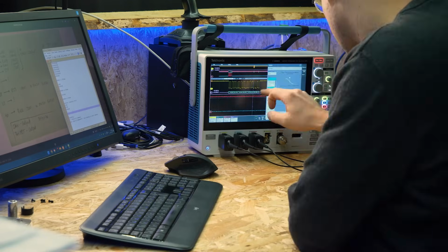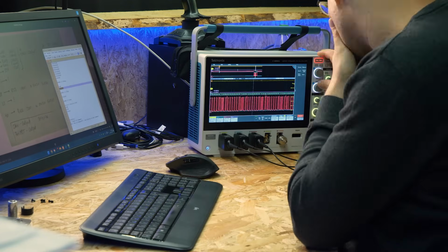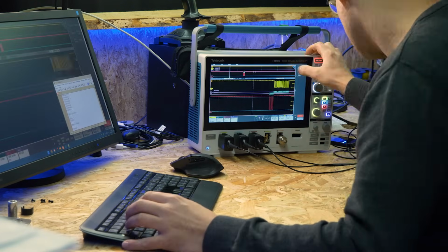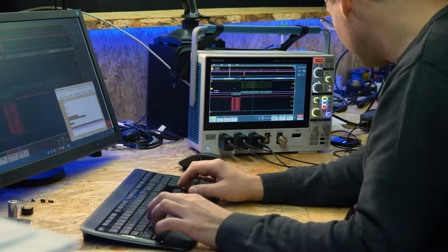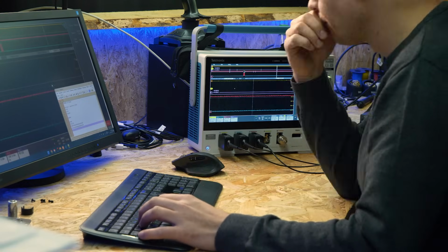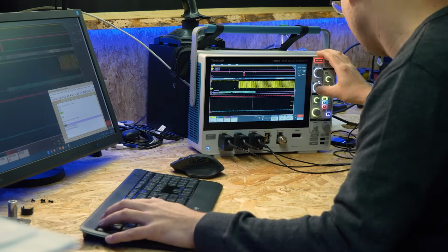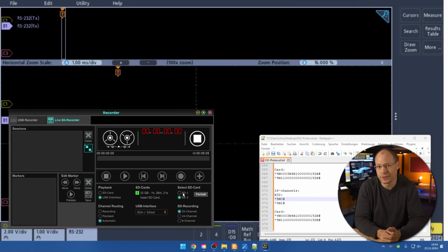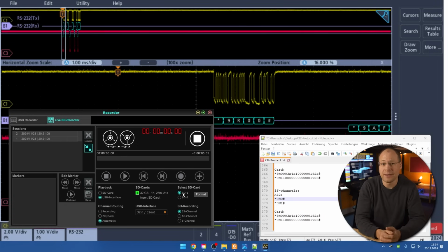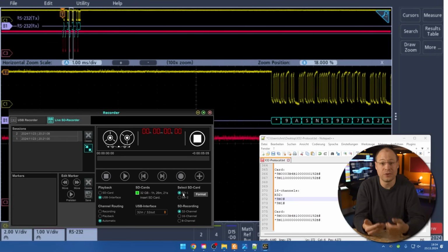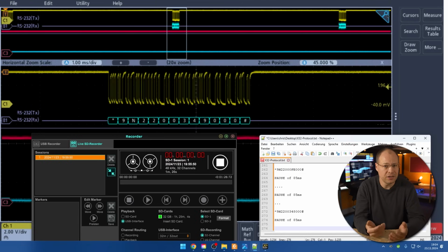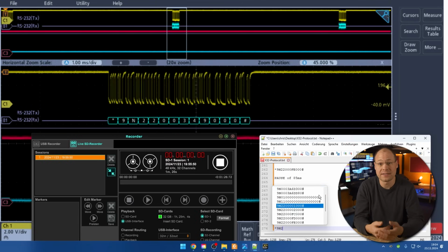Everything else was then painstaking work. I then spent over an hour sending various commands from the X32 edit software to the SD card controller and writing down the various commands. In total, I was able to track about 20 commands with matching responses. Here you can see, for example, the commands for listing the individual tracks on the SD card, and here the current position, which is sent from the card every 85 milliseconds as status information while playing some audio.